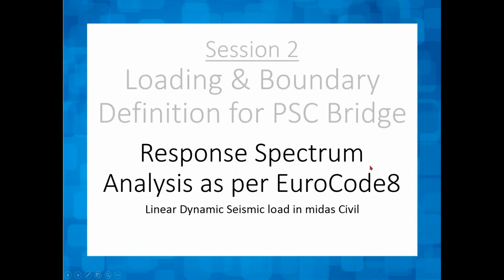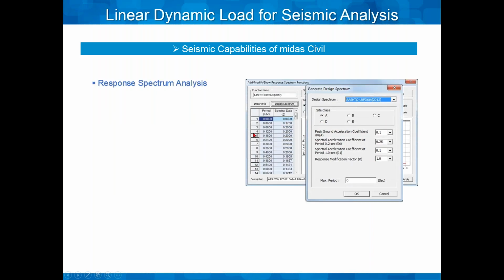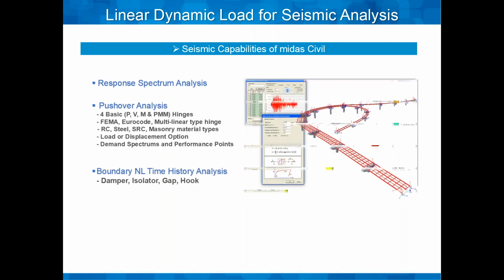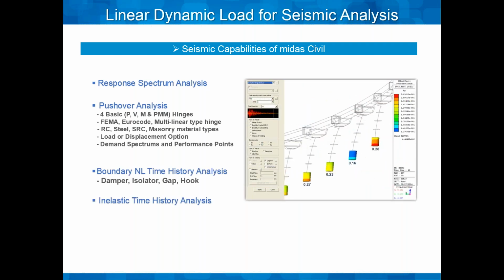Let's now go ahead and see how to apply response spectrum loads in MIDAS Civil as per Eurocode. So MIDAS actually has a response spectrum analysis, pushover analysis, boundary nonlinear time history analysis, and inelastic time history analysis. So response spectrum is actually our linear dynamic analysis.